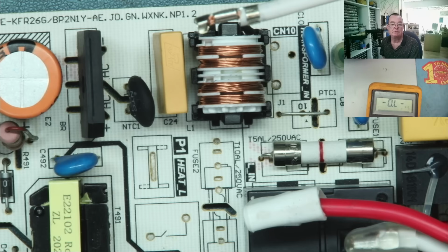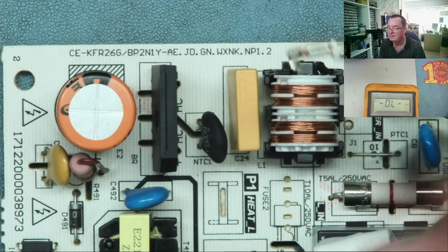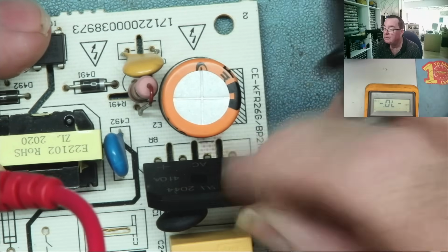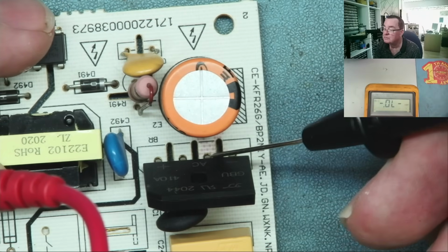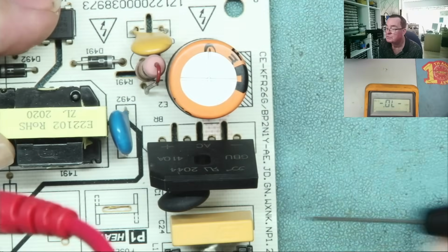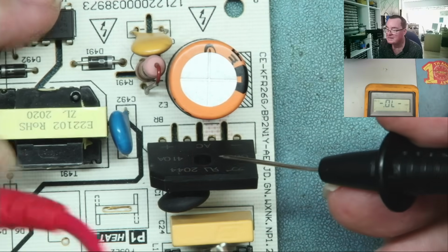So I was in ohms range, I'm now going to go to diode range. And let's check all the diodes. So there's 4 in here, this is a bridge rectifier. Okay. Can I see any markings on it? Yeah. Minus AC, AC plus. If you couldn't see, the slope is always the plus. And almost always the AC in the middle.